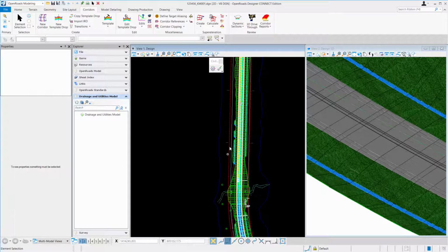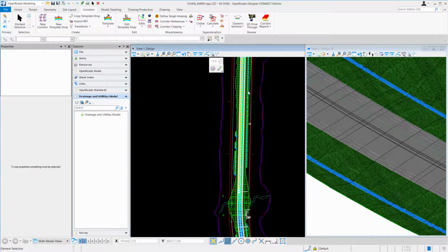So what I'm going to do is use a fixed ditch so I get a ditch through this whole thing. Then I'll take a look at the profile and make my edits where I want. You could easily focus in on a given area. You could do a normal template through, see where your fill condition is, and then maybe template drop that location and just create a ditch profile for that given area. You take what I'm showing here and apply it as needed.